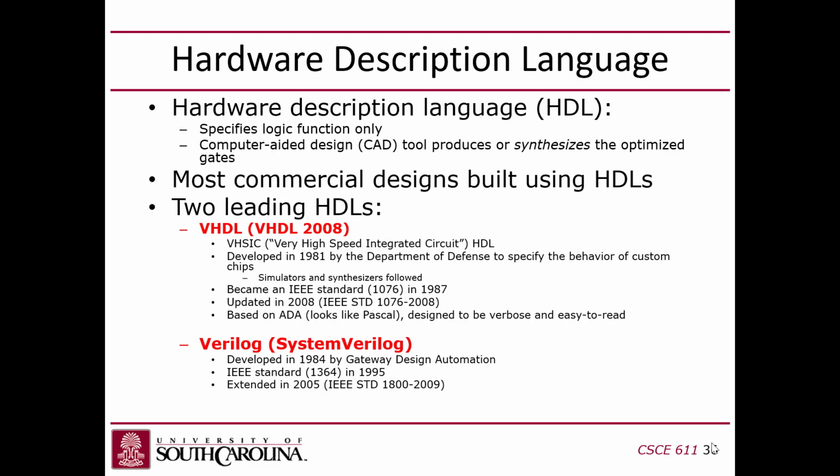SystemVerilog was designed to fix some of those idiosyncrasies, but it was also designed to extend the ability to write code for modeling. If you want to create models that are not intended to be synthesized, but just used for simulation, fake mock-ups of stuff that you can write at a high level, SystemVerilog brought in more power on that end as well.